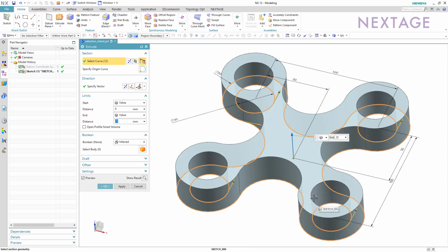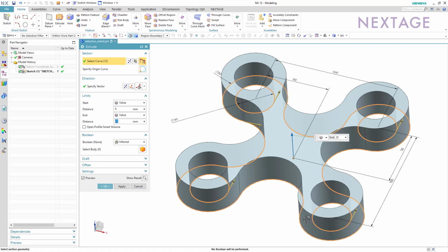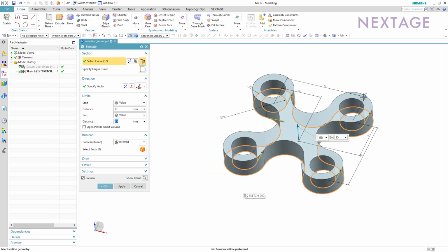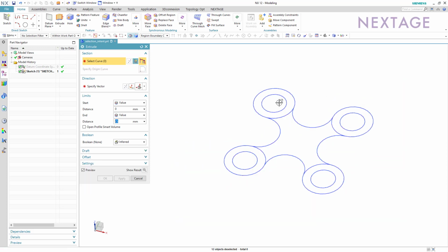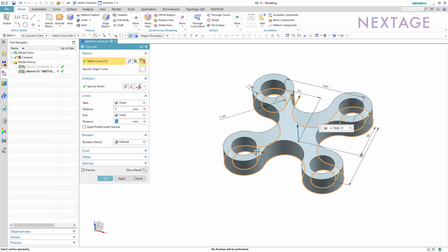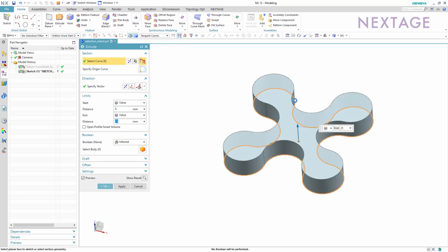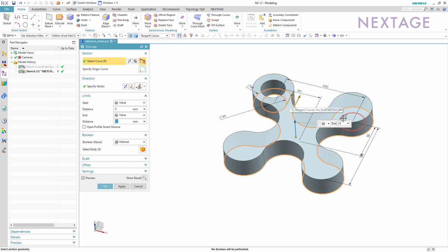And if you want to deselect, you hold down shift and deselect the curves. Okay, so just be aware that you select the region, but you deselect on the curves. And this here is about as efficient as my second method. So I needed a total of, if I just deselect everything here, 1, 2, 3, 4, 5 clicks. And if I reset and use the other method where I had tangent curves, follow fillet, we can see that I also need 5 clicks.